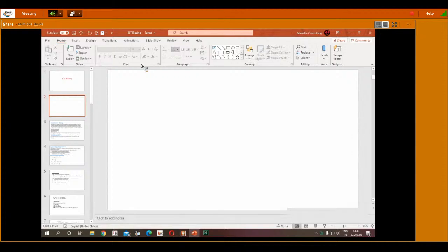To obtain a suitable configuration for amplification, which will act like a perfect amplifier, the common emitter configuration can be utilized as a general amplifier, since its characteristics (input resistance, output resistance, current gain, and voltage gain) are all near the range of the required ideal characteristics of an amplifier. Hence we are moving to our session with the common emitter.